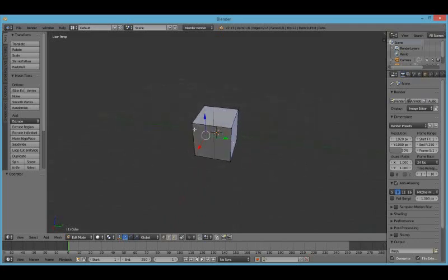Just quick, simple ways. The first is by pressing CTRL R, which adds rings. So these pink rings divide the mesh in sections. You can run your mouse around the mesh to try to get a feel for how it works. Scrolling up on the middle mouse button adds more rings. Left clicking sets it, and you can set it again where you'd like, where you can right click to auto center it. And press CTRL Z to undo that.